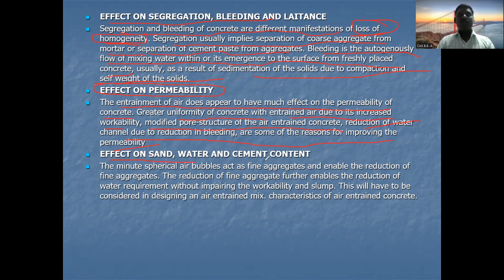So, effect on sand, water and cement content. Whatever cement, sand and water we are adding into the concrete, what is the effect of the air entraining agent on the sand, water and cement? That we will see now. Generally the minute air bubbles act as a fine aggregate. So the bubbles are forming if we add the air entraining agent, and the bubbles are acting as a fine aggregate.